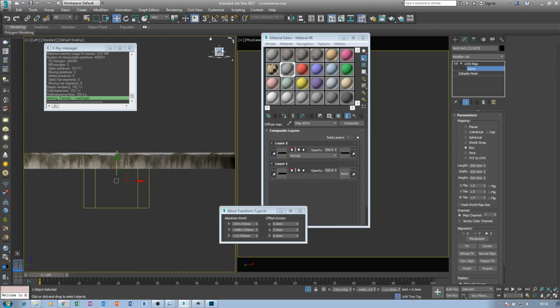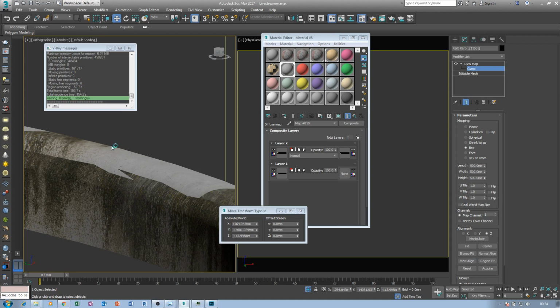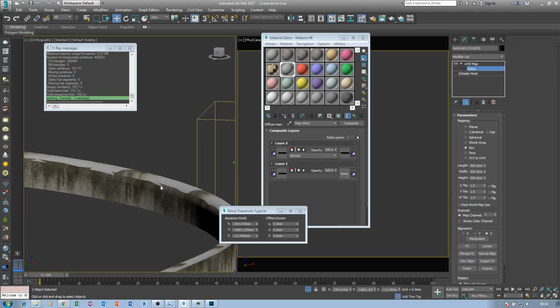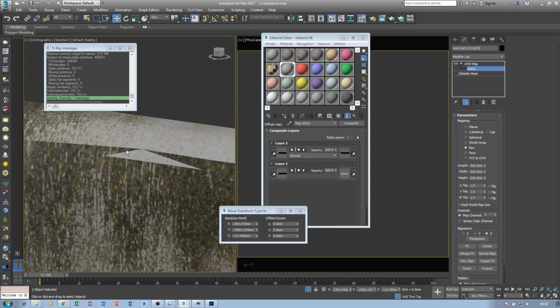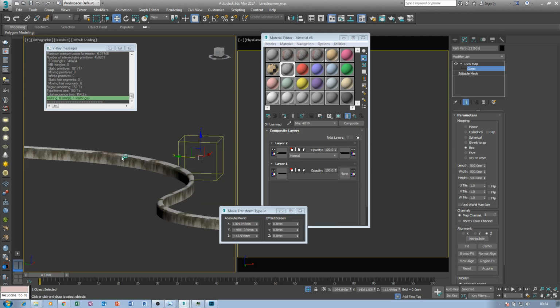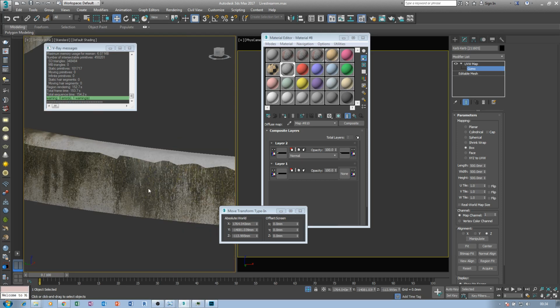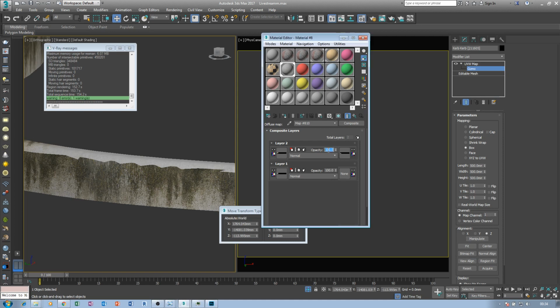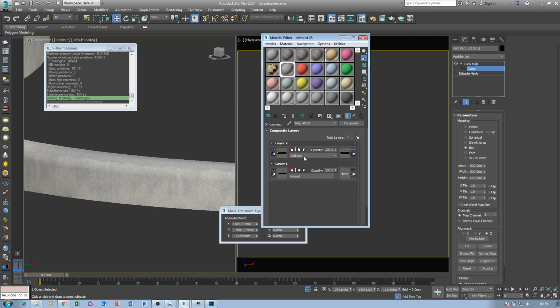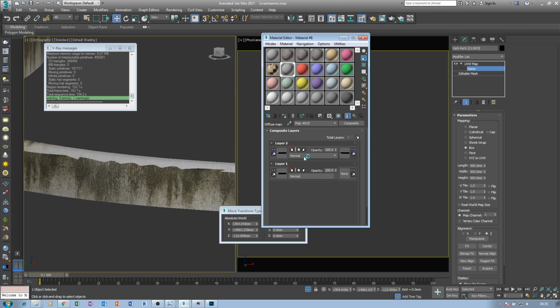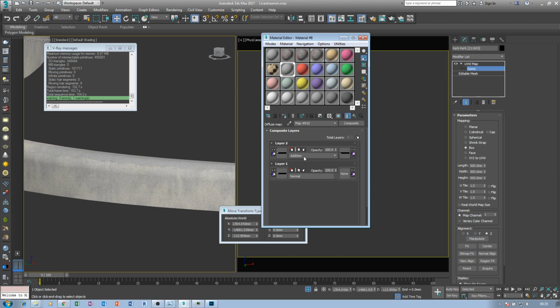So now one of the problems here is because this geometry is from Revit, so it's not giving me perfect faces, but yet you can see the way this thing looks, and you can change the opacity. So let's go on average. Let's see the way it will work. Now this average, this is just blending mode, how they blend together, and you can see this one blends, this one comes out well, then this one blends a little bit on the average, then addition is just like you are adding it, a small effect.